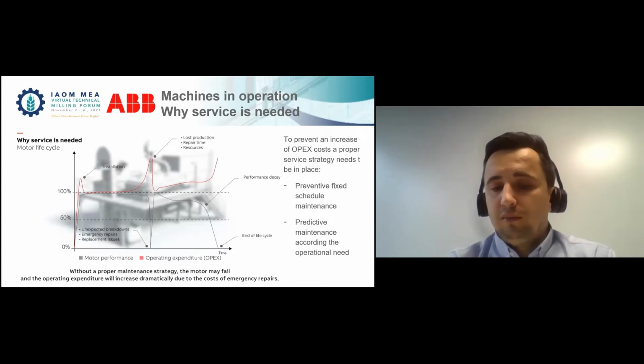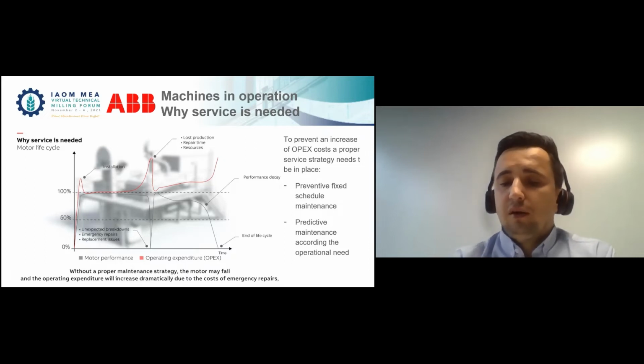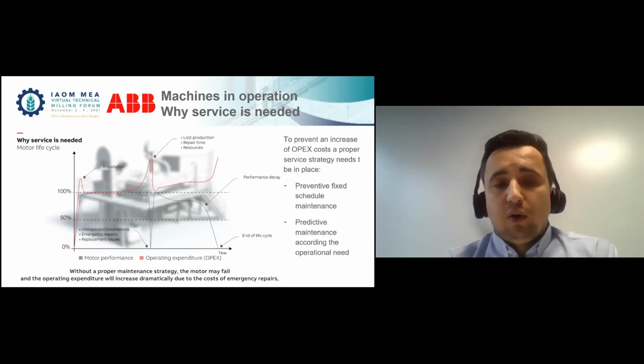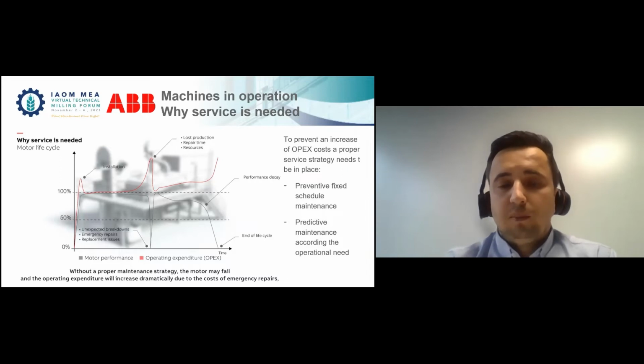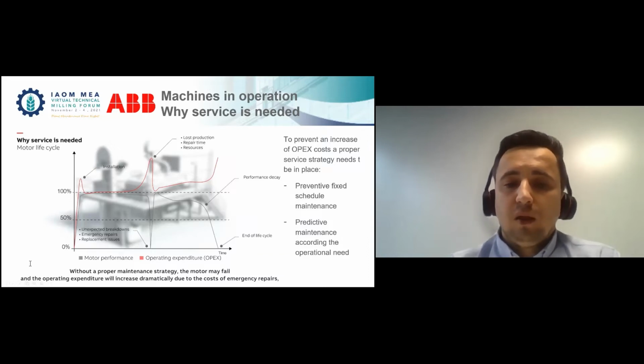You're doing it by a strict schedule according to your experience, manufacturer specifications and application requirements. So if you have a high temperature environment, high dust and everything, you shorten your intervals a little bit, so that the motor has no breakdown.